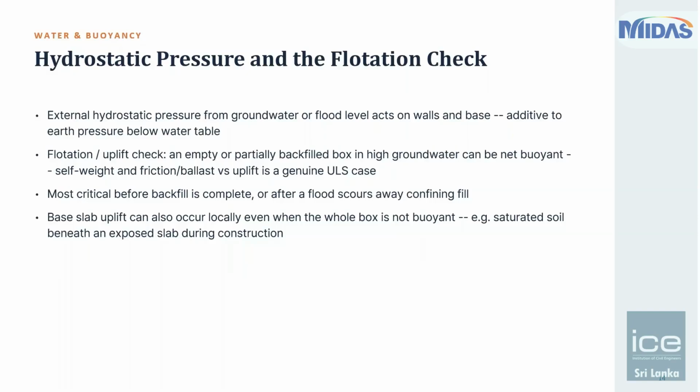This will give you a higher load on your walls for wall designs, as well as higher uplift forces, which might increase your forces on the base slab design, okay, which might increase your reinforcement in the base slab design on the top face. Also, apart from this, you'll have to perform the uplift check. These are some sort of stability checks that we need to perform in cases of uplift. But in culverts where you have a very high soil fill above the culvert top slab, this might not govern. But in our current case, where we have not assumed any soil fill height, right? There's a chance that when water uplift is present, the entire structure might lose weight and show uplift. Okay, so that is why we must account for that.